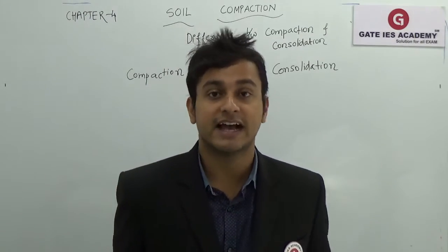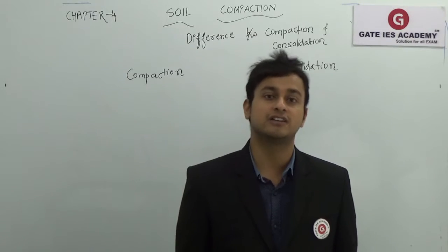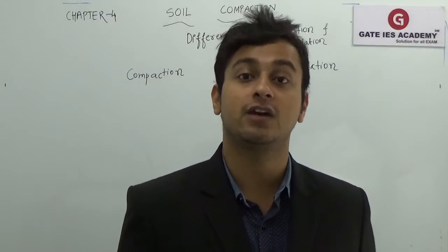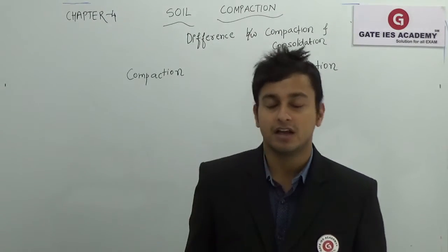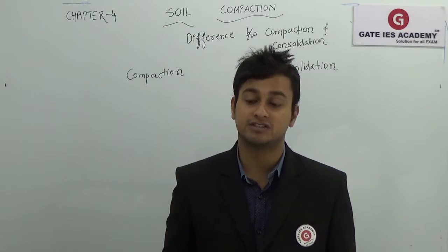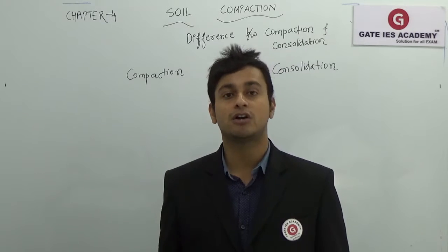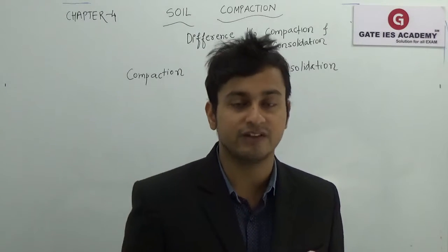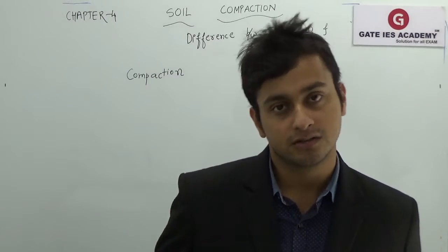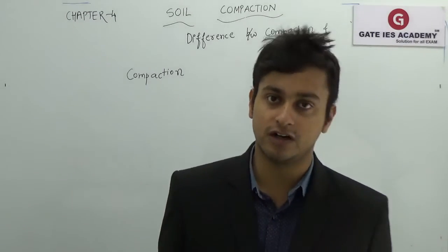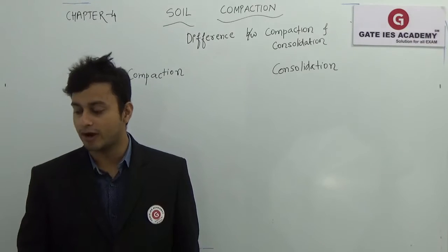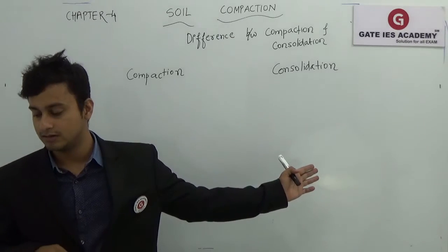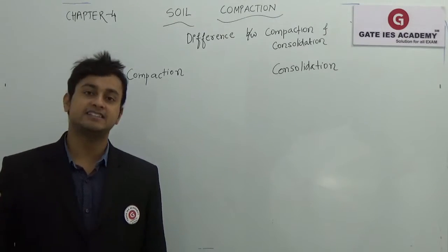Moreover, here we use saturated soil in consolidation and unsaturated soil in compaction, because we are basically dealing with the decrement of the air voids. Mostly in compaction we use dynamic loading such as rollers and tampers, which are provided for a particular amount of time, but consolidation is not dynamic loading, it is static loading, in which you just apply the loading and then allow the soil to consolidate correspondingly. So write down first point. First point in compaction is it is an instantaneous phenomenon, and first point in consolidation is it is a time dependent phenomenon.